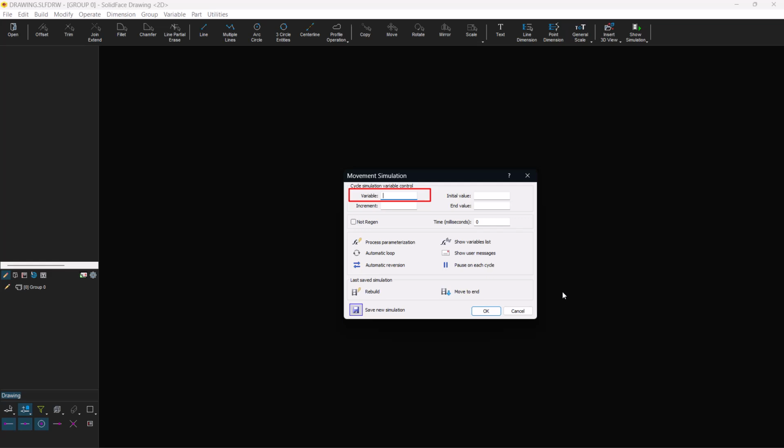In our example, we are going to show a connecting rod crank mechanism movement. The rotation angle variable used to rotate the mechanism's hand crank is also the control variable used to count the simulation cycles. When the simulation is complex, that is, with alternating movements, translation, and rotation, another variable is used to control when these steps should be set, normally by logical conditions.